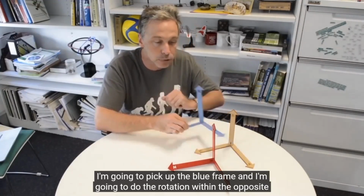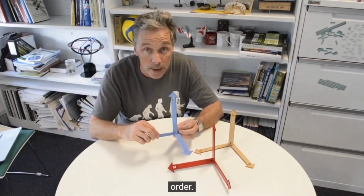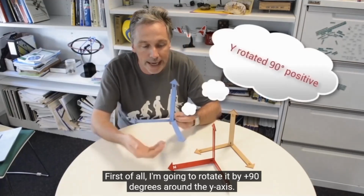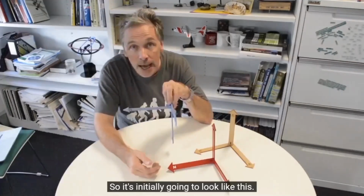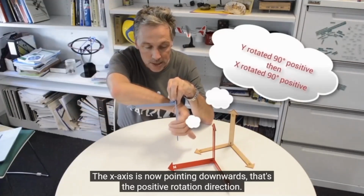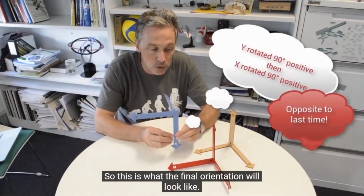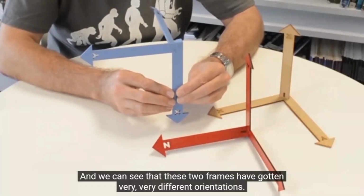Now I'm going to pick up the blue frame and I'm going to do the rotation but in the opposite order. So first of all I'm going to rotate it by positive 90 degrees around the y-axis. That's the positive direction, so it's initially going to look like this. And now I'm going to rotate it by positive 90 degrees around the x-axis. The x-axis is now pointing downwards. That's the positive rotation direction. So this is what the final orientation would look like. And we can see that these 2 frames have got very, very different orientations.